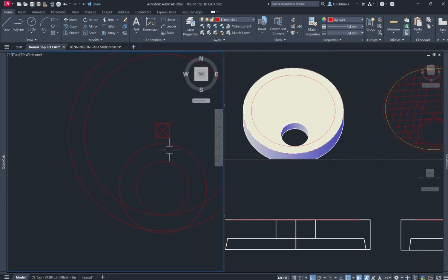Usually we put it at 1.5 times the slab thickness. So if the slab is 9 inch thick, I'll put it at 18 inches if possible. If not, then the minimum is the slab thickness, so 9 inch slab, 9 inch offset. That's the minimum. But as long as possible, just do 1.5 times the slab thickness. So that offset. And from the centroid we need 3 lifters.